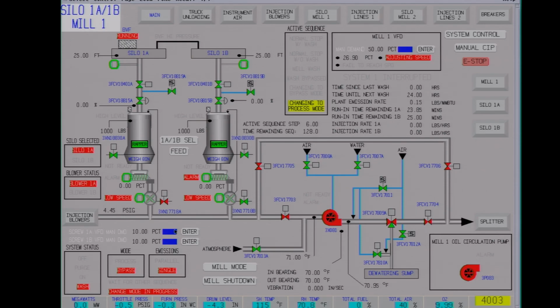Okay, we got the blower running. 4.45 psig coming down here. It's going through the Viper mill. These bypass valves are for when you water wash the Viper mill, because the product will build up on it. So use water to wash it. Speed slows down, water blows on it, cleans up any buildup, and then it goes down to the sump.